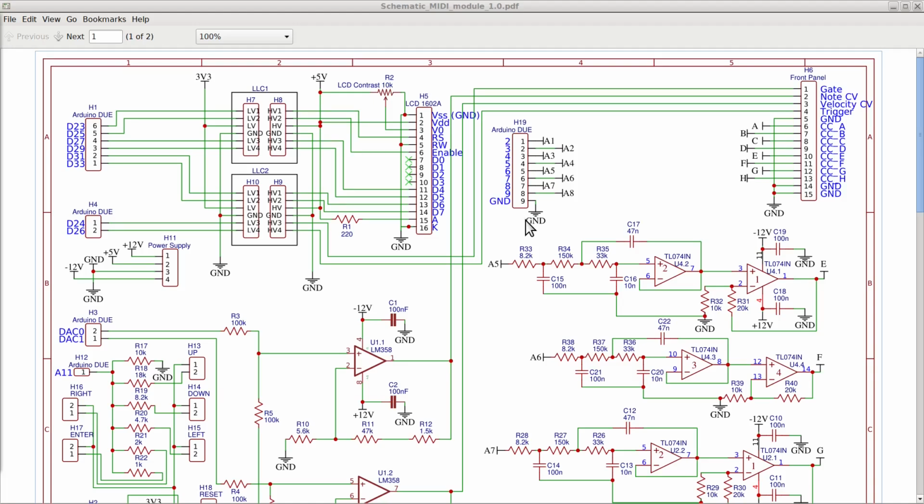Each pin from the Arduino goes to the input of a third-order low-pass Sallen-Key filter, adjusted for a Q of about 1 to avoid both under and overshooting, and a cutoff frequency of about 80 Hz, which is 1 order of magnitude lower than the frequency of the PWM waveforms. The characteristics of this filter allow us to remove entirely the square wave component of the PWM waveform, leaving only the average voltage, which is what we need.